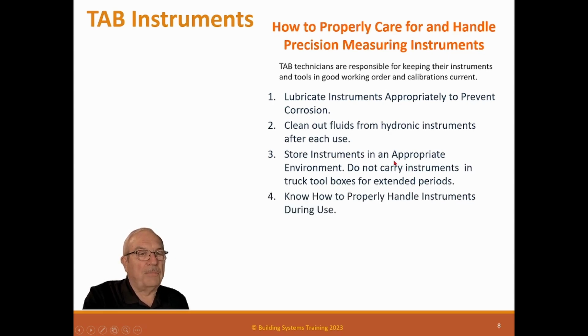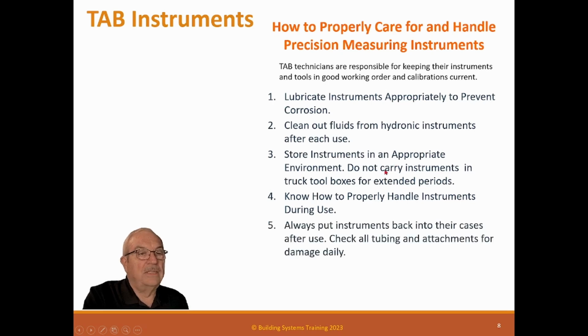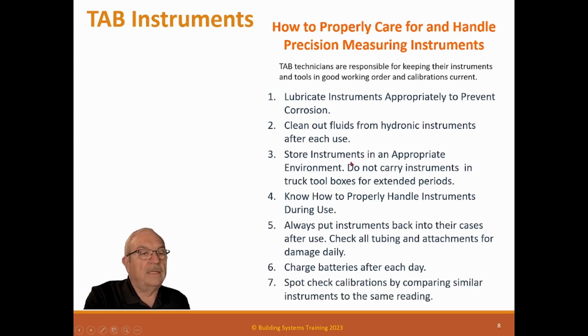Know how to properly handle instruments during use. Always put instruments back into their cases after use. Check all tubing and attachments for damage daily. If you have pressure tubes and they get a hole in them, now you're not accurate anymore, so you need to make sure the tube's in good condition. Charge the batteries after each day if they're rechargeable batteries. All this is important.